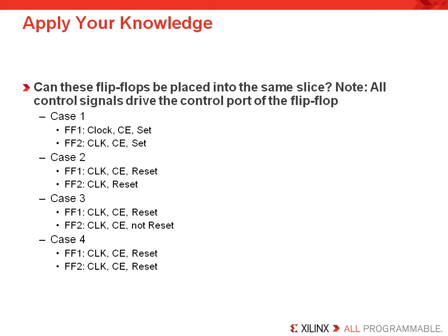And so you really have to ask yourself simply, can these be paired into the same slice? Well, in case number 1, the answer is no. The flip-flops have different clocks, so they're members of different control sets and cannot possibly be grouped into the same slice. So that's just not going to happen. Case number 2, flip-flop 2 has a high, or VCC, as the clock enable. So even though we don't have a clock enable defined for the behavior, because one does and the other does not, that effectively defines there being separate clock enables. So likewise, those can't be grouped into the same slice as well.